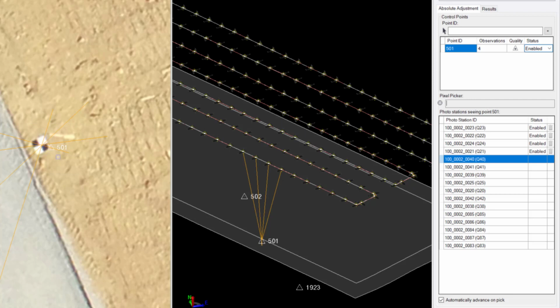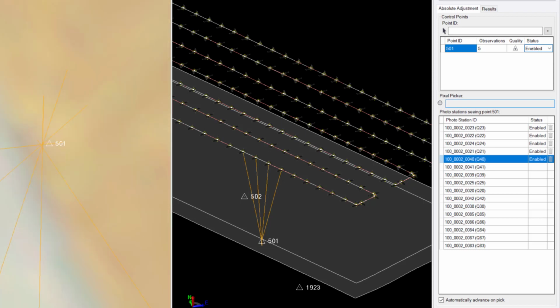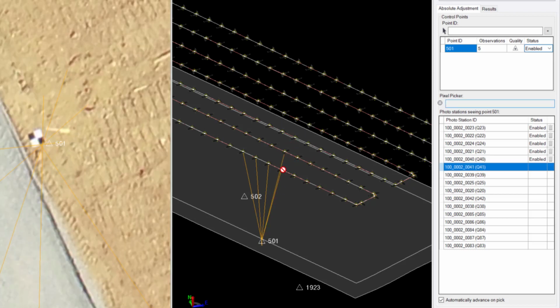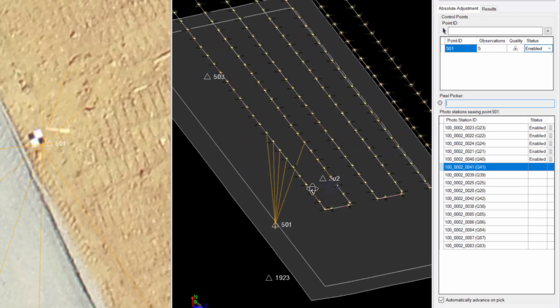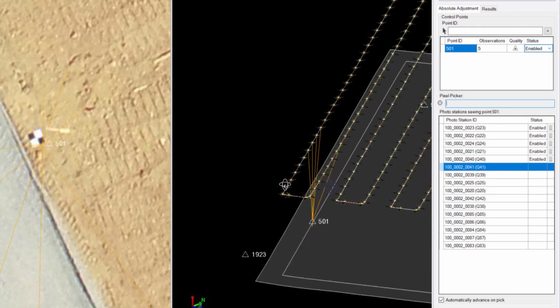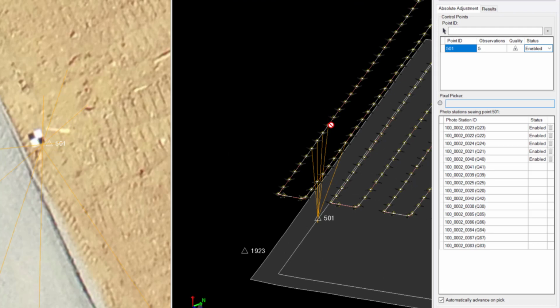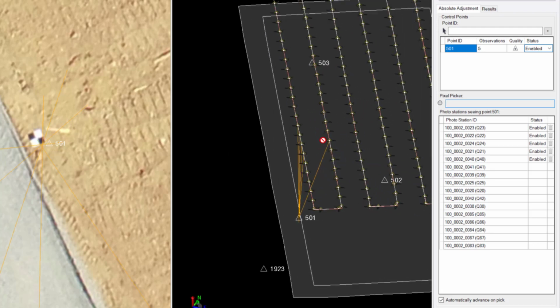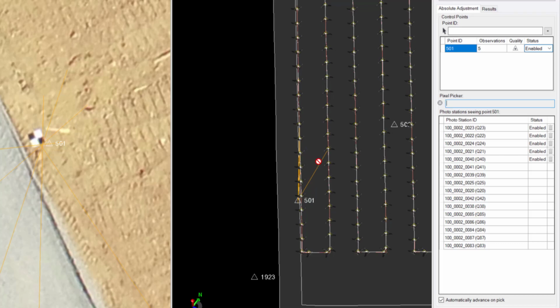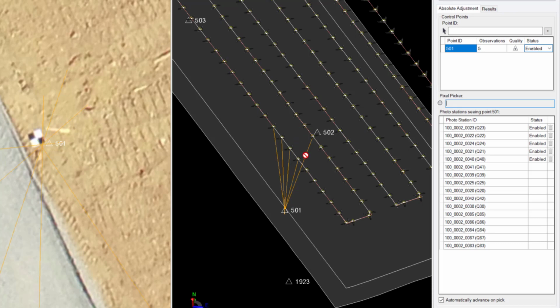It's just that there is some shift between the GNSS and the control point. So I can now make the measurement, click it here. And now we see on the right side on my part my new line of sight. And this is really what we definitely want. We want to have measurements not only from 1 strip, but at least from 2 strips. And it would also be good not to have just 1 from here and 4 from here, but perhaps 2 or 3 from here and 2 or 3 from here. And if they are even visible in this 3rd one, then also 2 or 3 measurements from there.